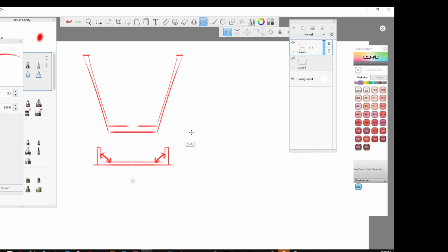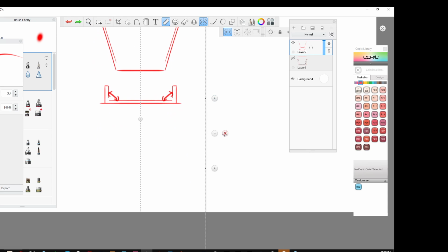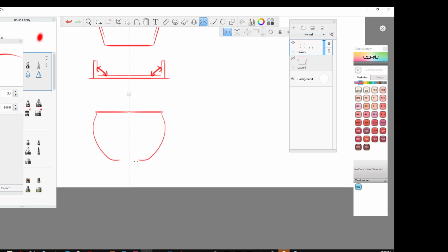Because if you have to do 10-degree draft on something, let's say, so I show my model and my sketch has this beautiful form, like that. We'll say that's a beautiful form. Well, the reality is, if I have to have that much more draft on there and I have to have something that comes out like that, well, that's going to look way different. So in the end, someone sits there and says, well, why doesn't this look like what the ID people showed us? And the engineers have to explain, well, they didn't design it for manufacturing. So it's not that during our initial rough sketches we have to do that.